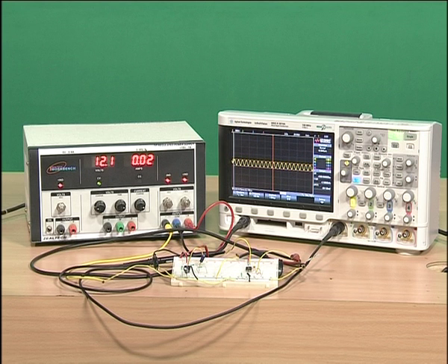The components required here will be a power supply source, a signal generator, and an oscilloscope to observe the signals. The passive circuits will require R and C, and the op amp circuit, which is used for providing gain in the pass band, is constructed with IC 741. IC 741 will require plus 12 volts for VCC and minus 12 volts for VSS.